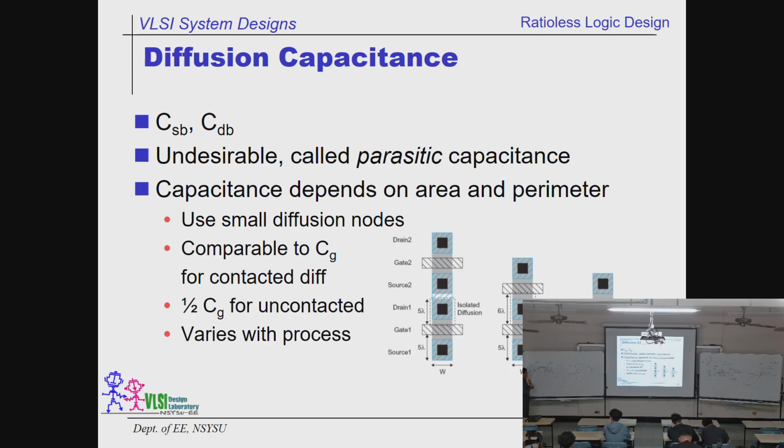The second thing is that there is a minimal requirement of a space between two transistors. So you have to sacrifice a space over here. This is to be sacrificed. As we said, the area means the cost. So not only is this design slower, it's more expensive. That is why we can use a better design in the middle.